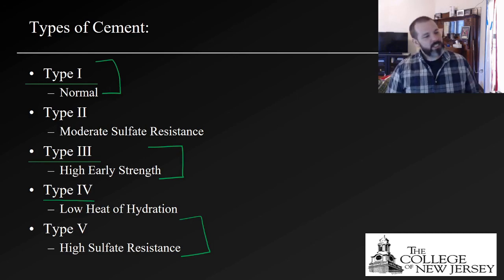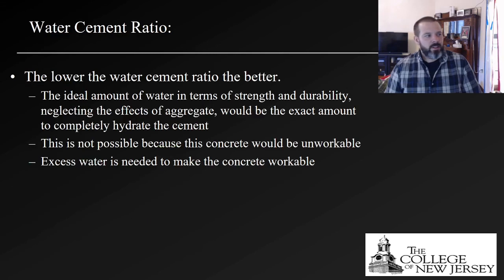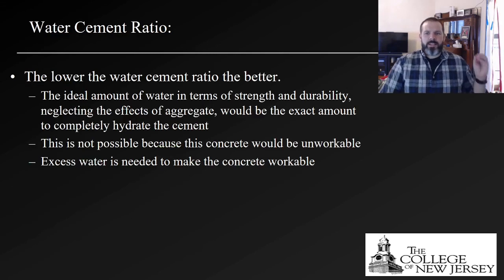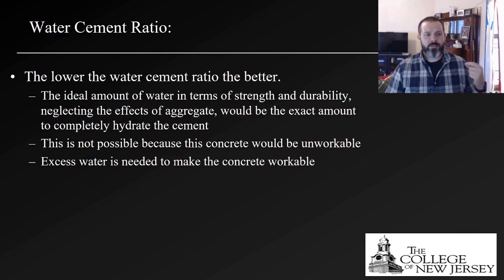But what's really interesting is if you make concrete, it starts curing, you put your hand to it, you can actually feel the heat coming off of the concrete. Now, the key to everything is the water-cement ratio. The lower the water-cement ratio, the better. The ideal amount of water in terms of strength and durability, neglecting the effects of aggregate, would be the exact amount of water to completely hydrate the cement.